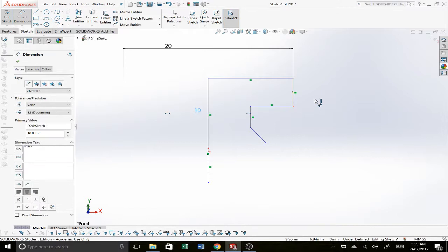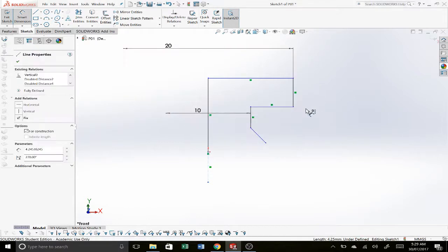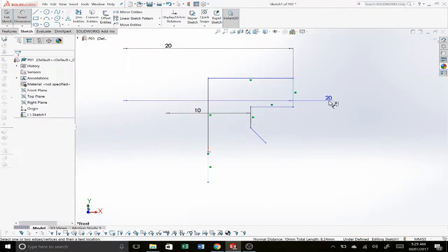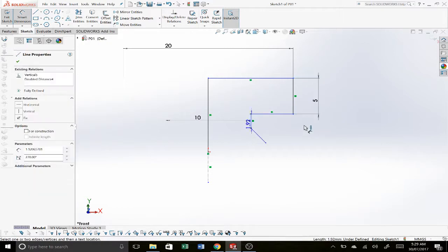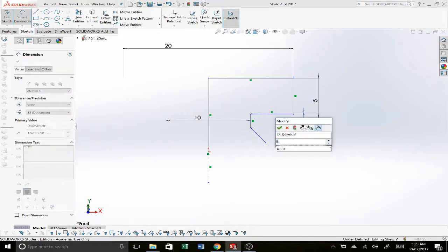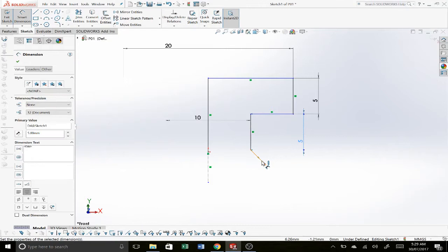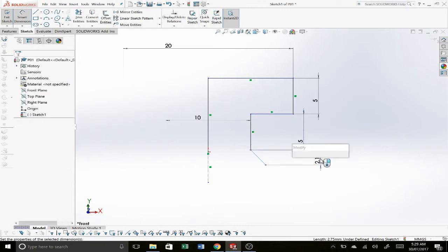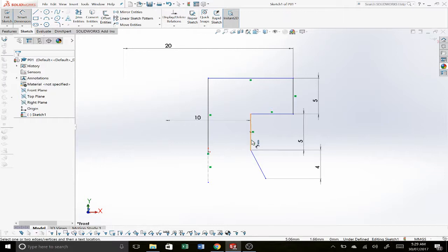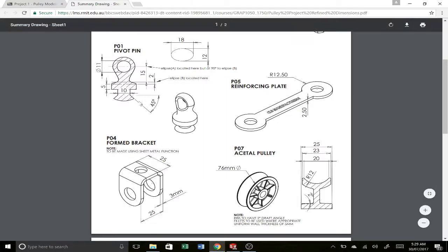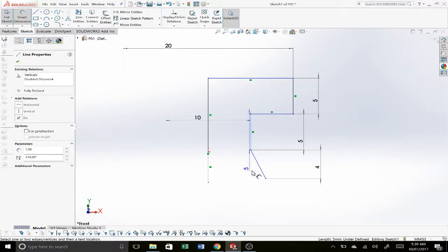And then that same drawing showed us that this section here, I'm just going to click off into white space because that center line was still selected, and we can see now that's behaving how we wanted. So I'll put a 5mm there, a 5mm here. I reckon that last one looked just a little bit smaller. I might chuck a 4mm on that. And I can see that's all sort of drooping a bit low. I want to put my angle on there, which I know is 45. And finally, we're going to draw just that little basin shape on the bottom there.